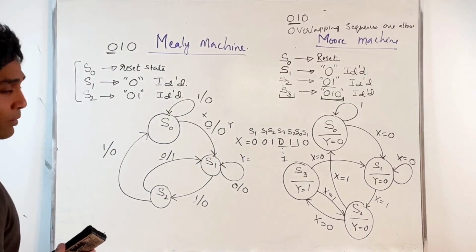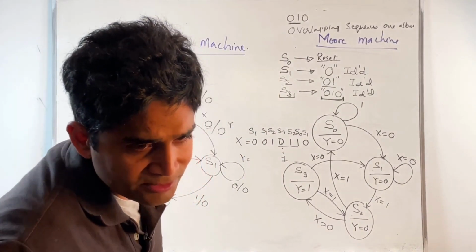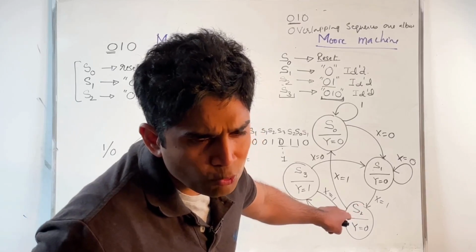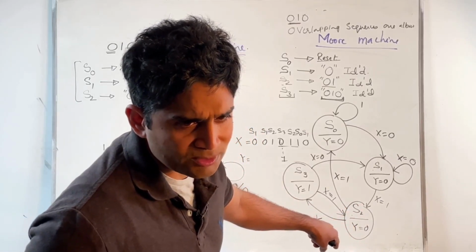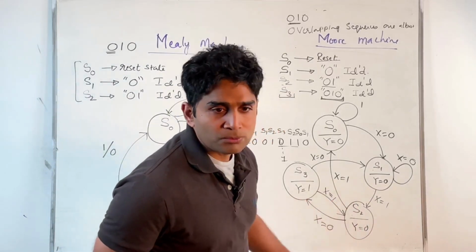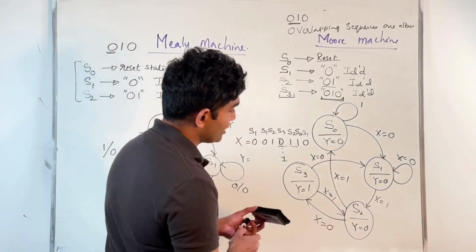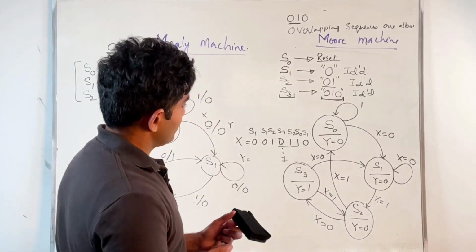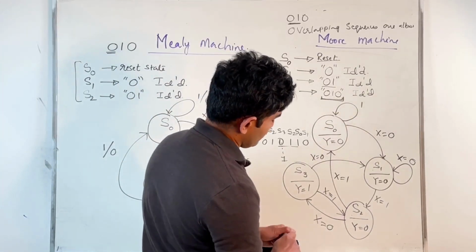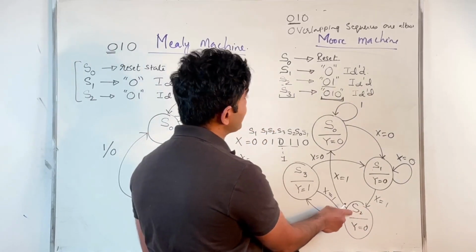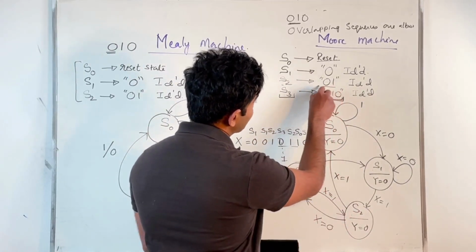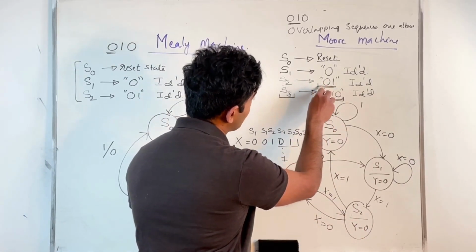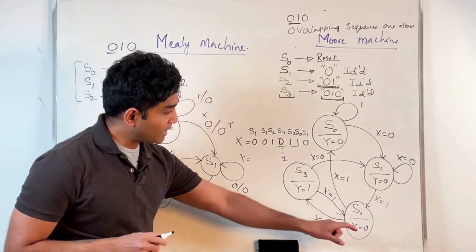Okay. Now, when you are at S2 and you have a 0, what is the reason why it cannot go back to S1 and forward to S3 with overlapping sequences? Okay, what is S2 state? Why can you not go back to S1? Let's say I'm in S2 state. What brings me to S2 state? This particular sequence in the input stream brings me to S2 state, right? If I have identified a 0, 1 in my input stream, that brings me to S2 state.